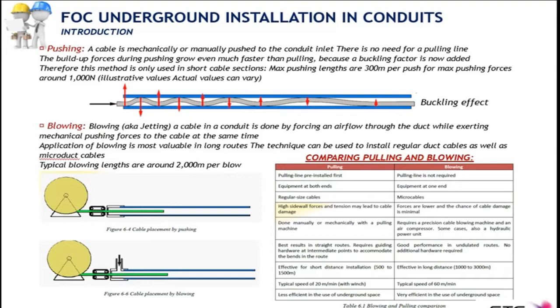However, the blowing and this cable floating allows the method to cope as well with bended routes, undulated routes. Therefore, the pulling may be effective for short distances, but the blowing is effective on much longer distances.